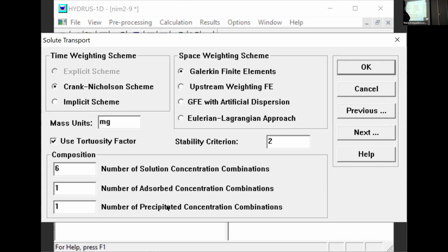They collect from 0 to 25 centimeter, as for example the root zone, or 0 to 40 centimeter. They mix the collected soil and give one sample to the laboratory. So the data correspond to the specified layer.